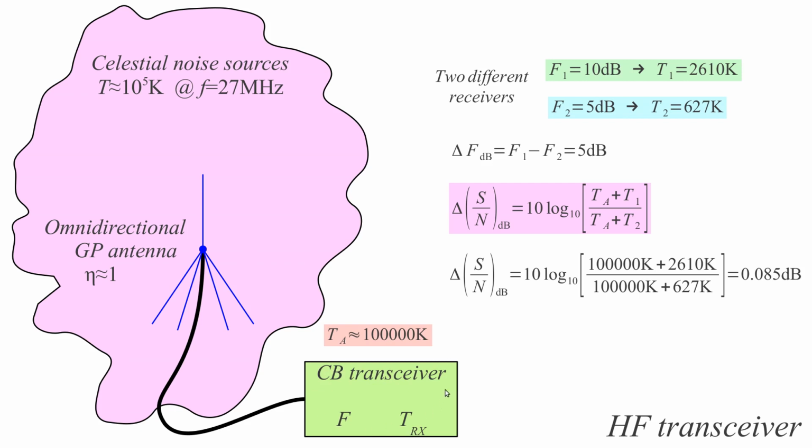This citizen band radio transceiver was using amplitude modulation. Some are also using FM, but with amplitude modulation, your noise is proportional to the power received from the antenna. And in the HF region, so below 30 MHz, the noise temperature is very large. The noise temperature of the sky, galactic noise, also some planets of the solar system, like Jupiter, is radiating lots of noise on HF. And in fact, this was the first noise discovered by Karl Jansky back in the beginning of the 20th century, and this was the beginning of radio astronomy.